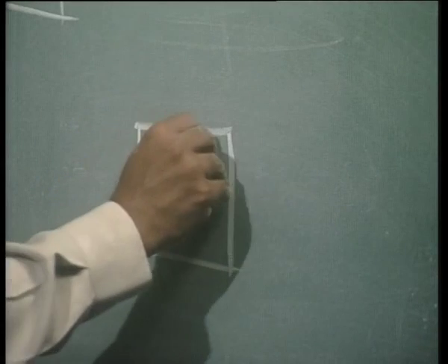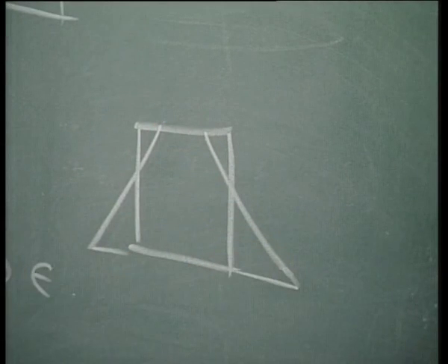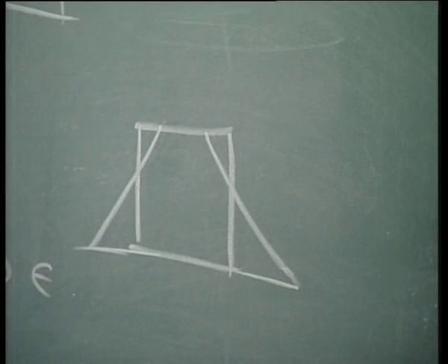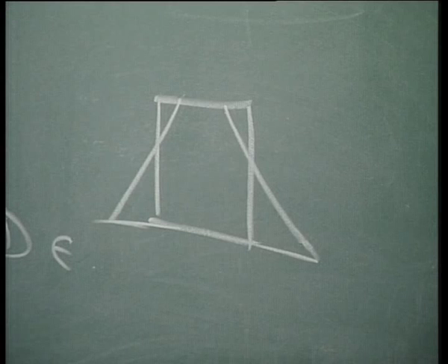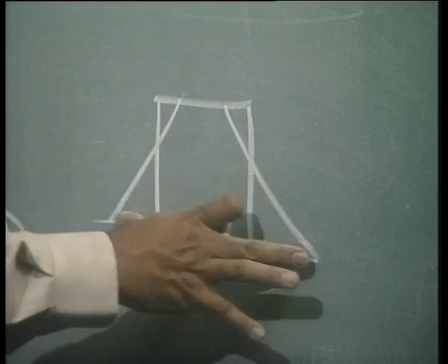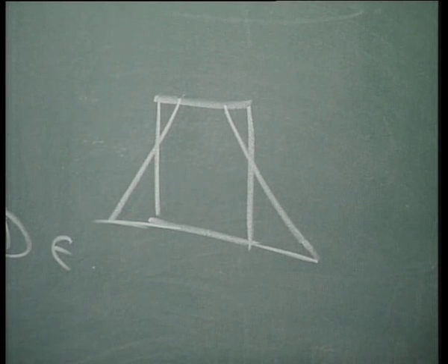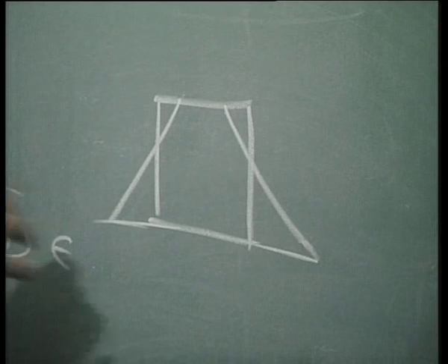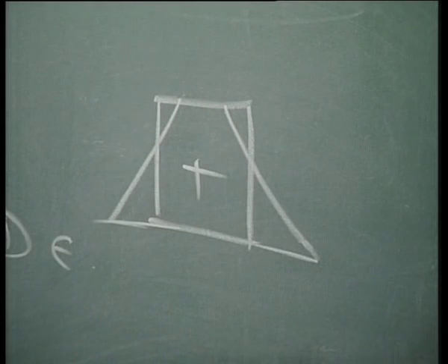There are other issues in it, but let us not worry about that. Let us say that this element bends and deforms something like this. There is, say, compression at the top and tension at the bottom, and so this element becomes like this. Let us say that I am using a 1/1 rule. What am I doing here? I am doing reduced integration. So what I am doing is trying to find out the strains at the center.